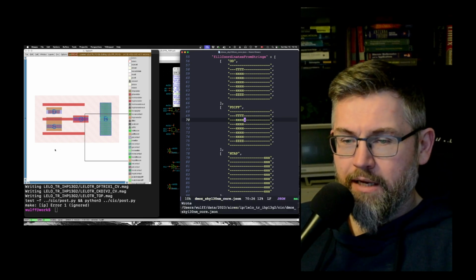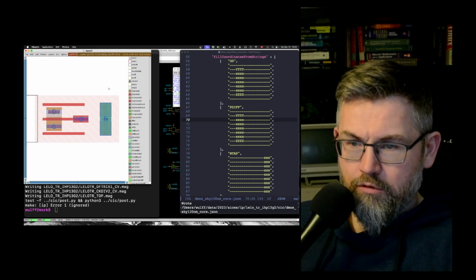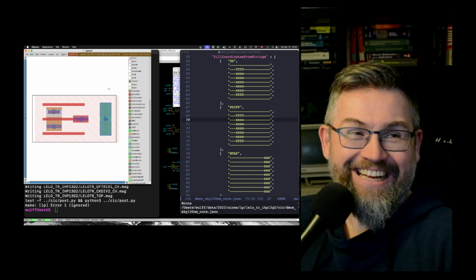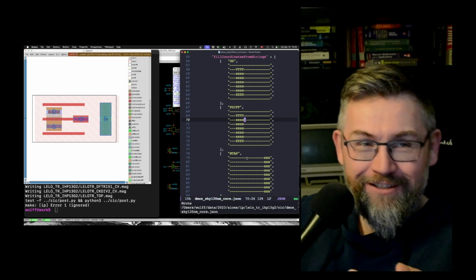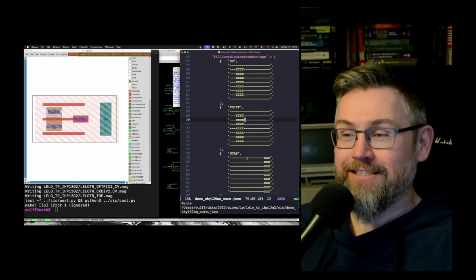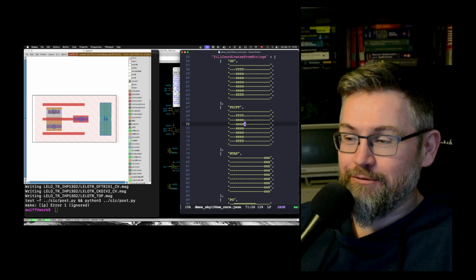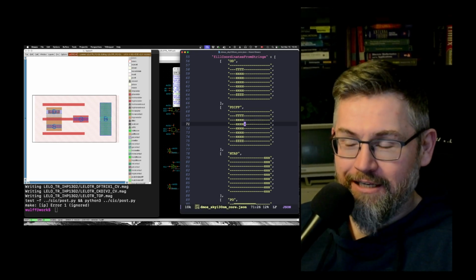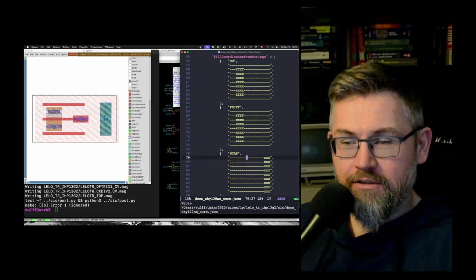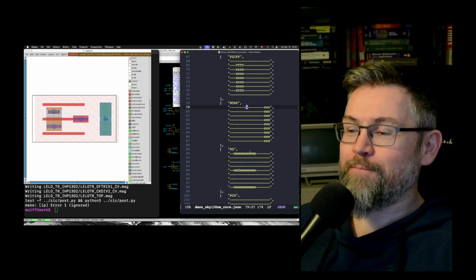So it's a bit of a pain though, because of course, in order to make it DRC clean, you have to sit there and modify. And modifying this ASCII art is actually as cumbersome as you would imagine. You sit there and you remove a couple of rectangles and you generate again and you figure out, is it clean? So that takes a while. But once it's done, it's done. You don't need to touch it.